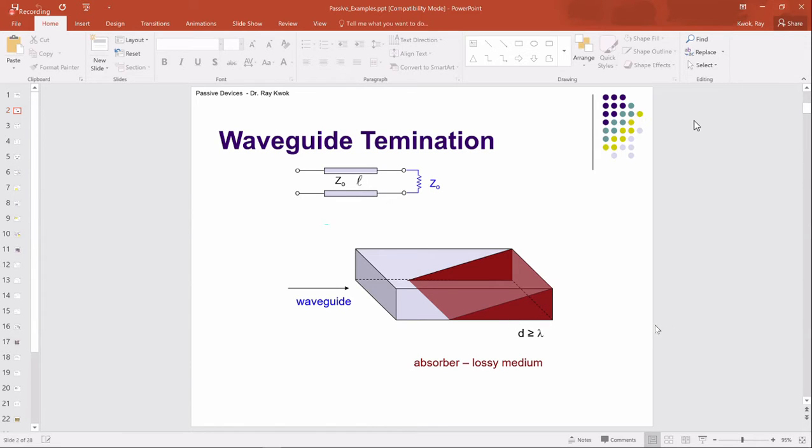Right. Quick question, Professor. Yes. So does it actually physically cover one end of the waveguide? That's what causes the reflections? Yeah, so you actually cut a piece of material. Like in this case, I make it simple, just a triangular wedge, and then just put it inside, epoxy it inside at the end of the waveguide. So there's a physical piece. There are different shapes. People do different shapes for different reasons. Either they have to handle higher power, widen the bandwidth, and whatnot. But the simple shape can be something like this.